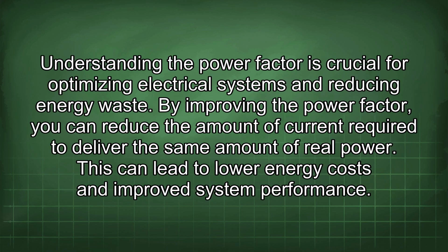Understanding the power factor is crucial for optimizing electrical systems and reducing energy waste. By improving the power factor, you can reduce the amount of current required to deliver the same amount of real power. This can lead to lower energy costs and improved system performance.